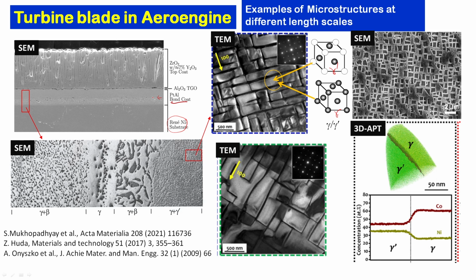So gamma prime is the majority phase here, you can see here these kinds of structures are gamma prime, and gamma prime is the ordered structure of gamma. Gamma is an FCC nickel based structure, where you have random arrangement of atoms at the atomic level. On the other hand, gamma prime will have a specific arrangement of atoms, the face centered positions are occupied by nickel and corner atoms are occupied by aluminum. Why? Because it is a Ni3Al structure. So therefore there are 3 atoms of nickel and 1 atom of aluminum in the unit cell.